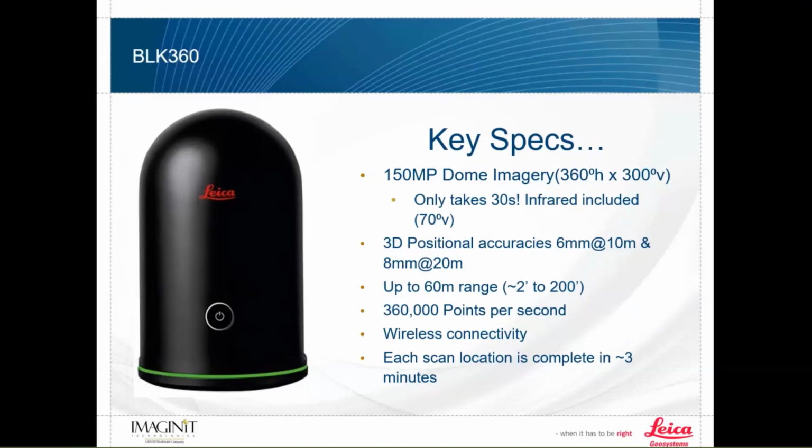And then each scan can complete within less than 3 minutes. So depending on the settings we use, we can have it take less time. We can have it take more time. And those are all based around how much you want that point cloud coming from the BLK360. So do you need to collect just every detail within a room, or are you looking for a general layout of a room?